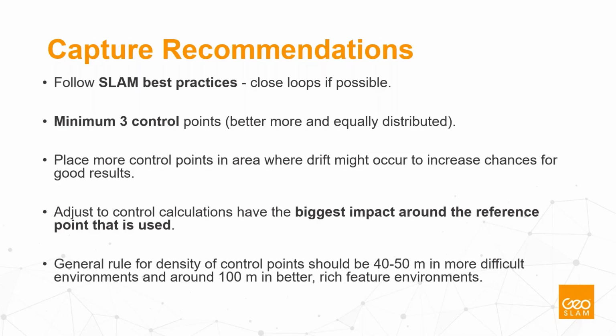A minimum of 3 control points is required, but definitely recommend to use more for contingency if the reference point detection is not successful on some of the points. Definitely try to keep more than 3 points per project to perform the Adjust to Control. The Adjust to Control has the biggest impact around the reference point that is used. The further away from the control point you go in the data, the less impact that the processing will have on the point cloud.